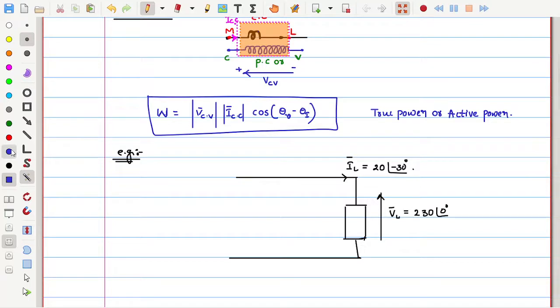These are the voltage and current. Now try to observe. If I connect the wattmeter over here, I insert the current coil here, where the current coil is connected in series with the load where we need to measure the current.